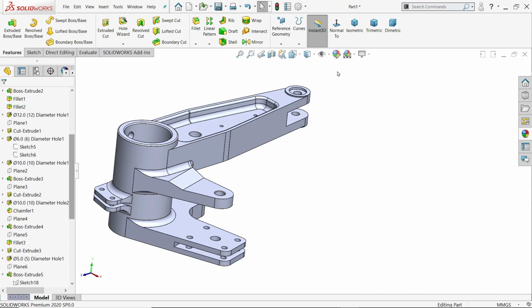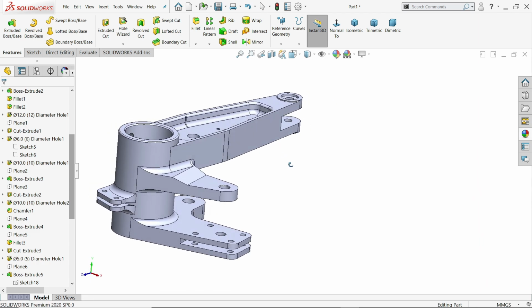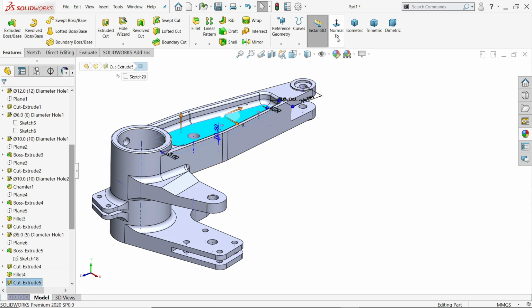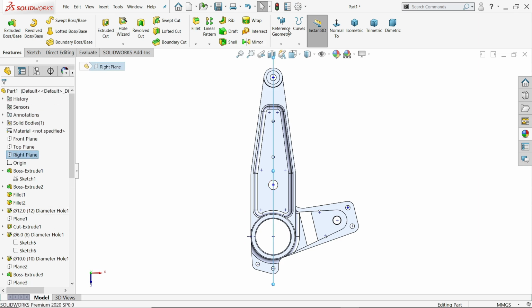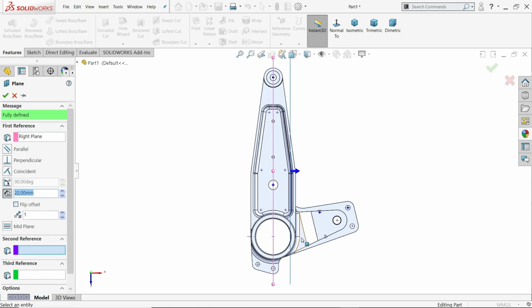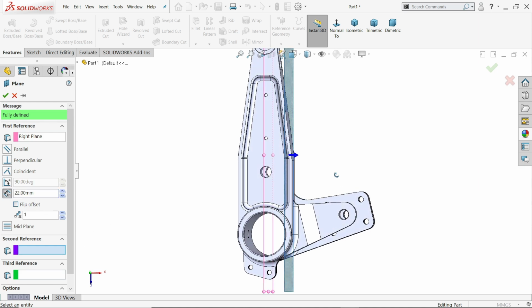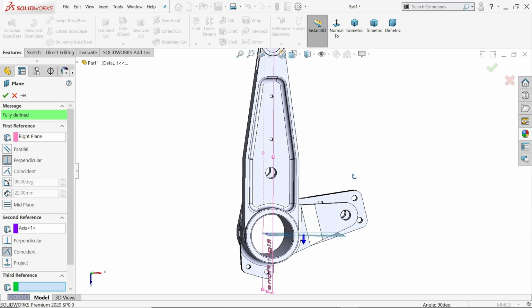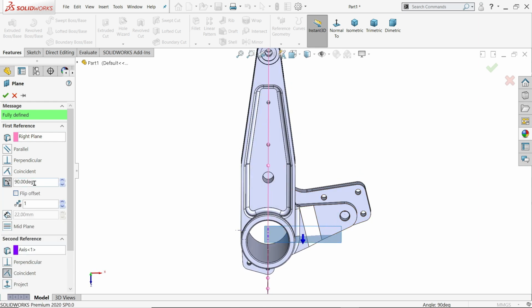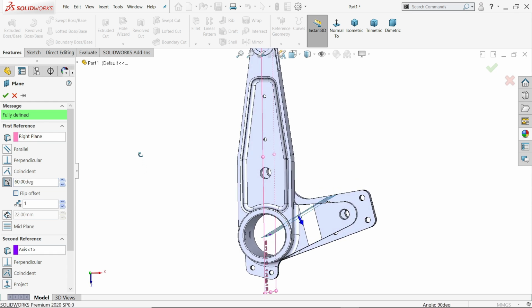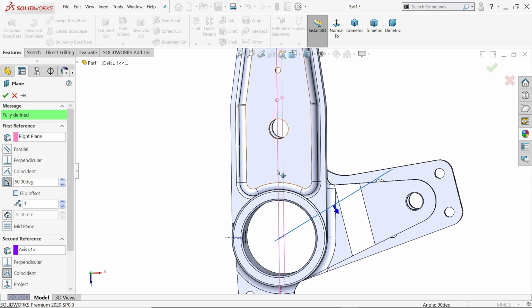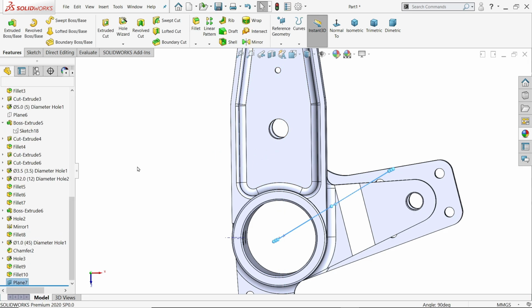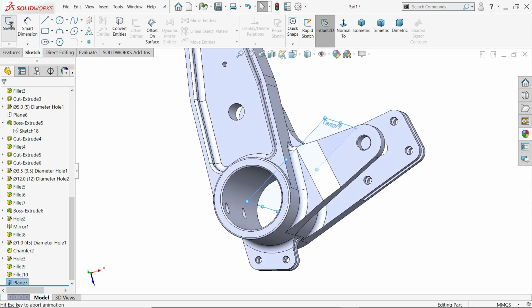Let's choose the right temporary axis. If I select this view, okay, we're going to create a plane like this. So I'll choose right plane. Plane. Okay. Now one more reference. So I'll choose, okay, this axis. Activate angle 60 degree. Now look, if we create it in this position, then we are able to create a hole at center that cuts through at 30 degree, because if you check perpendicular, it becomes 30 degree here. Say okay. Now I'll okay.